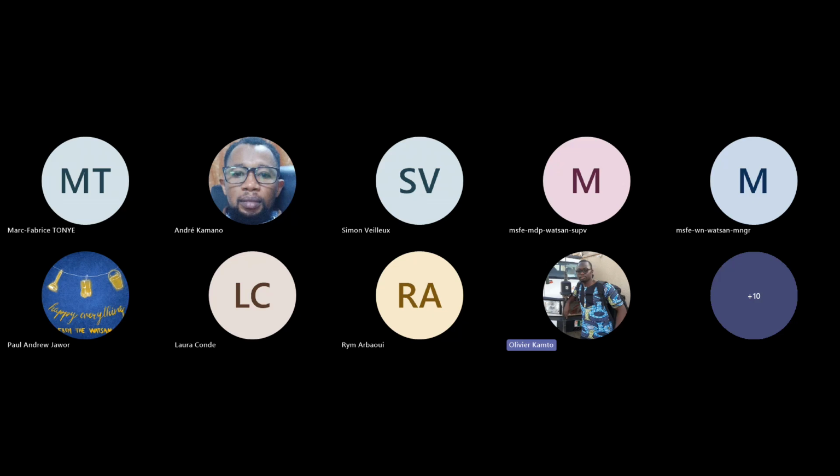So we would generally recommend starting from the needs. Sometimes we may find a Q0 that is very small compared to what the borehole can produce. That is fine, because we are looking for a Q0 that will give us the amount of water we need to respond to our needs. If the needs increase, then we can consider doing the pump test again: we define Q0, and then we run the pump test.